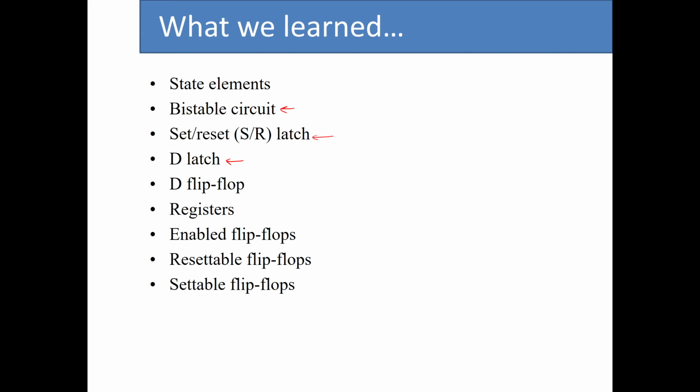So we said let's move further with this design to the D flip-flop. We can only change the output of the D flip-flop in a very short period of time. The D flip-flop basically samples signal D on the rising edge or the falling edge of the clock, depending on the design that we have. Because of this, D flip-flops are more common in sequential logic circuit design.